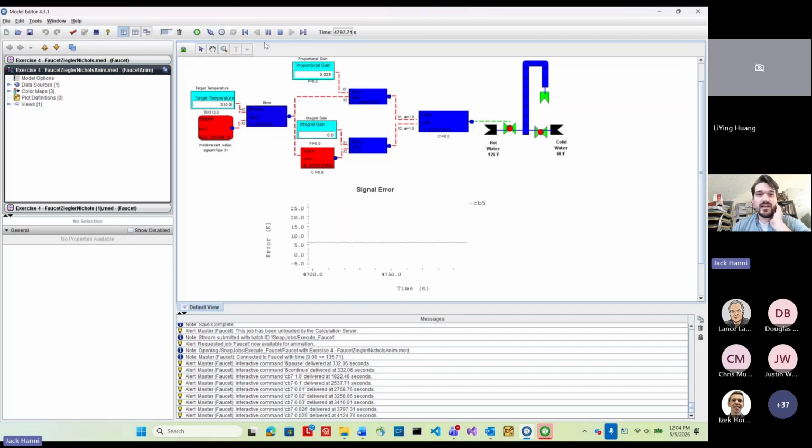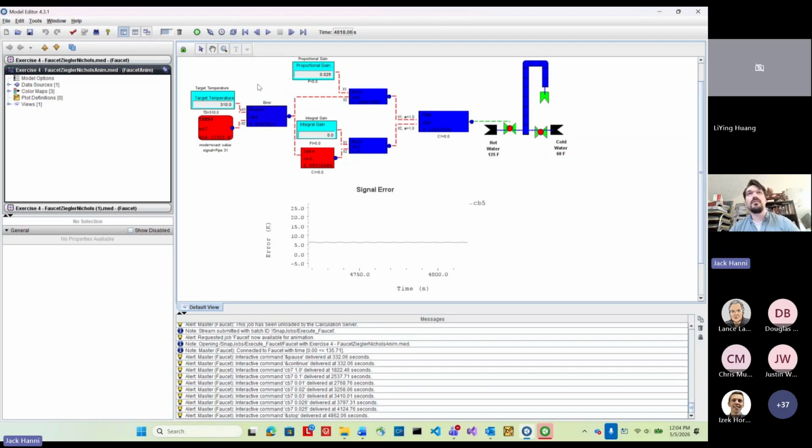And then Ziegler-Nichols, that method tells you to multiply that value by 0.45, which is roughly 0.0117. And then we can restart just to look at this plot.